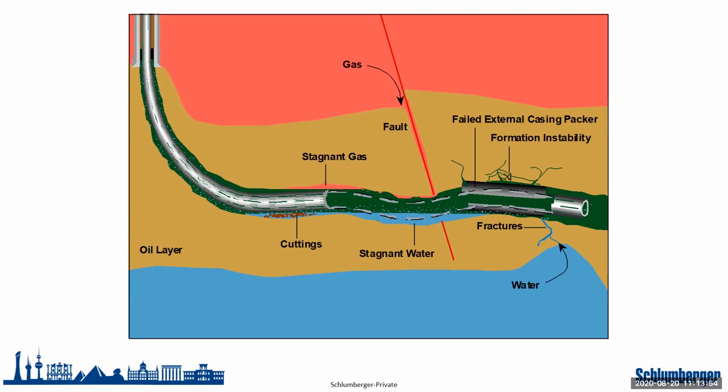Not only that, once your deviation increases and gets near to horizontal, you will start getting fluid segregation, okay? So another thing that is going to be challenging, in a highly deviated well, the method of conveyance of your tool is going to be different. To be able to drive the tool to the bottom of your logging interval, you will require either coil tubing, okay, or you will require a tractor. A tractor is a tool that drives your logging tools to the bottom log interval, okay?